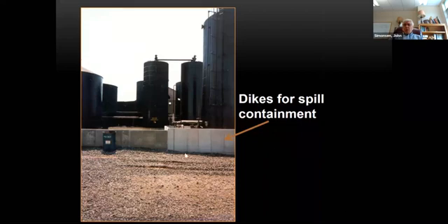So now it's required that you have dikes all around all of your storage tanks so that nothing can escape, and you have dikes around the cylinder. As I mentioned, you have a drip pad so everything can drip until it's done dripping. Or you put it in a kiln and heat it up, because that will also speed up the process of converting the waterborne chemicals into insoluble chemicals, especially with CCA.